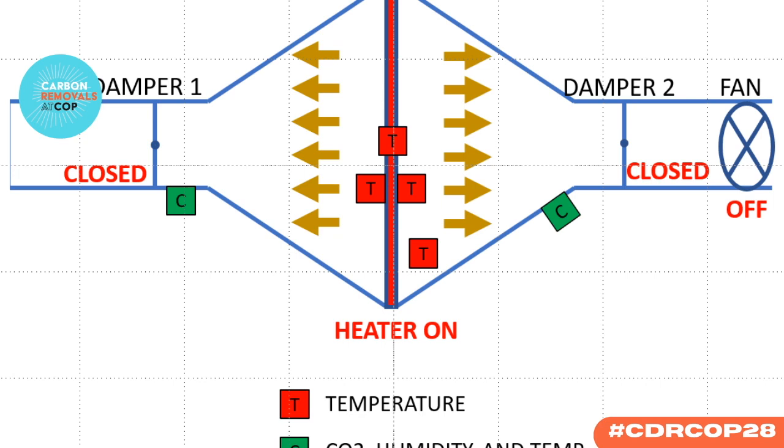And this is as far as our development got. But what would be needed going forward would be to add vacuum to it, which is not shown here. The desorption process will work a lot more efficiently and give you a much purer CO2 output if the sorbent is heated in the presence of a vacuum, and then the pump can pump the released CO2, say, into a tank or into some other device that would process it.